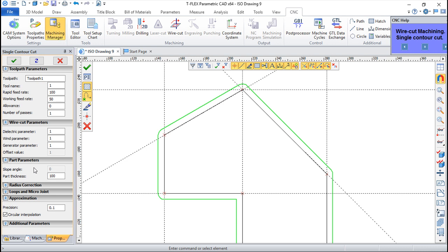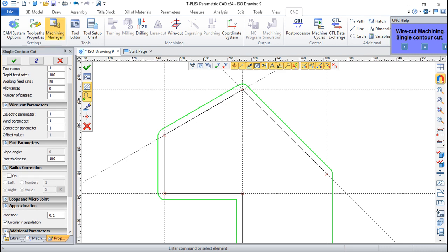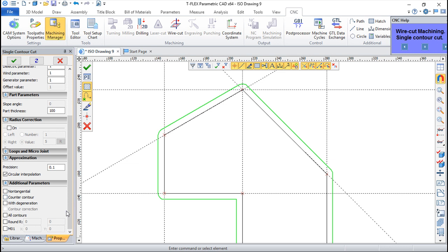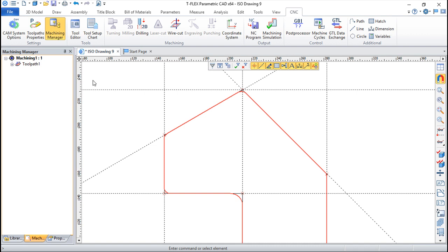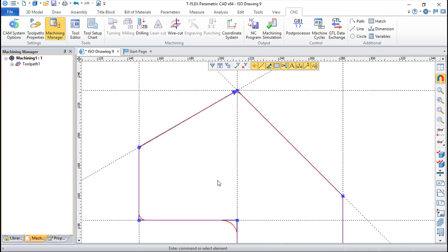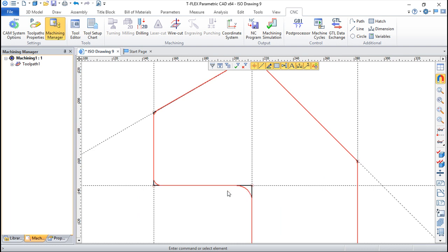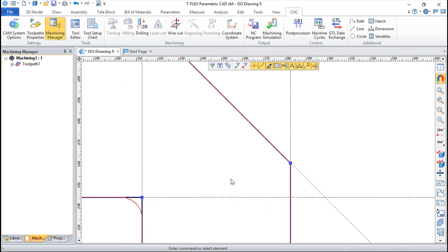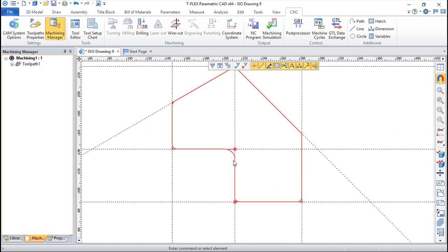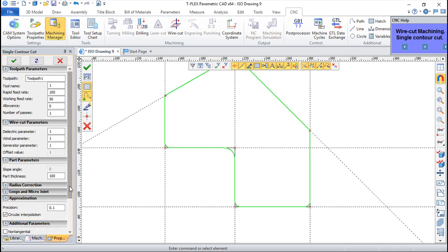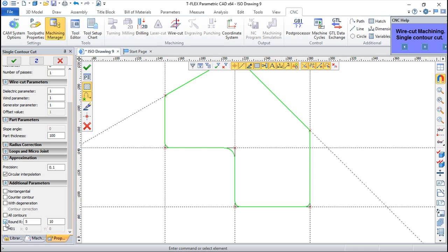And we can have also, let us take this correction, radius correction out. Let us open, take this out also, and say rounding radius, which we can define in our geometry. You see, it will make one exterior radius as one value and one interior radius as another value, okay? So this is also a very interesting option to work with, and which does not need to have geometry done. It can be done with parameters.